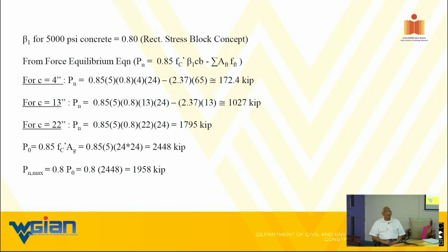But in spite of it all, why your structures are not as durable, I don't follow. Is there some material issue? Yes, actually one thing Professor Surya told in the morning, that is water cement ratio. It's hardly controlled normally. Well, I thought you all said now we are controlling it to 0.4. Yeah, but at lower levels, there is not that much supervision.